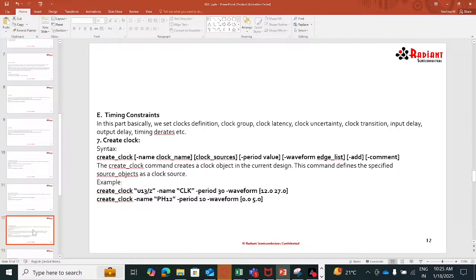Okay, so when we are defining a certain portion outside of the blocks, that portion of the period will be removed and the remaining portion of the period will be utilized for our current block. The same applies for into range and similarly for range to out. Okay, and then lastly, timing derates.